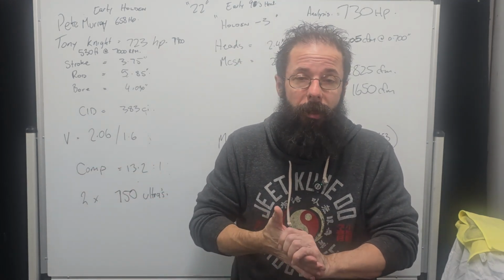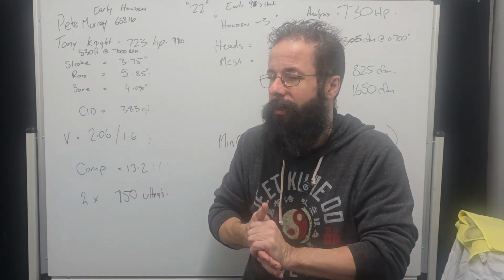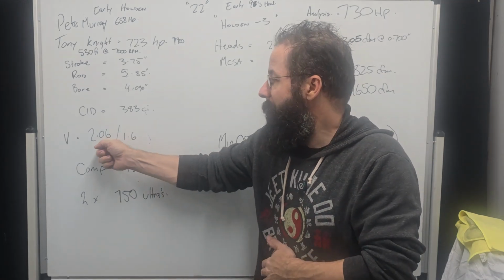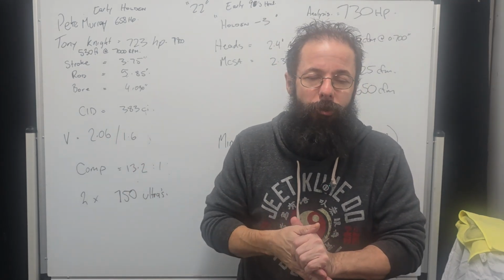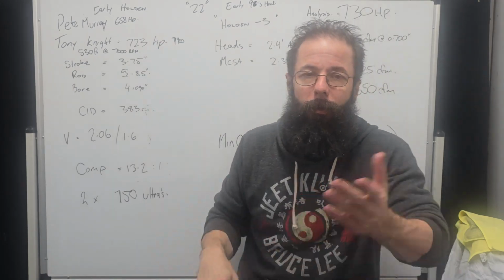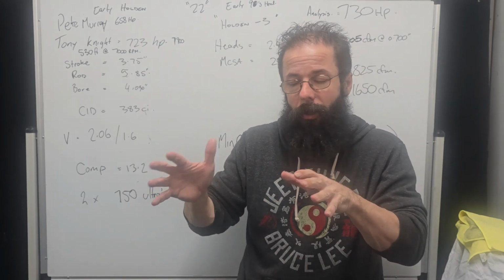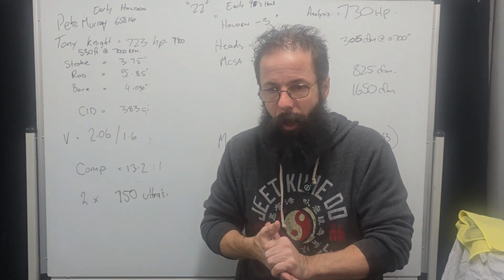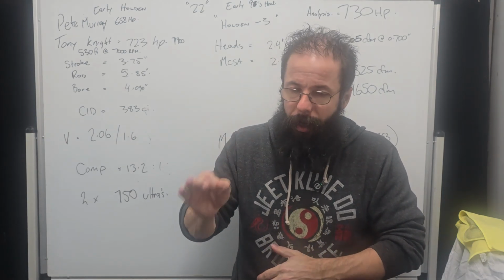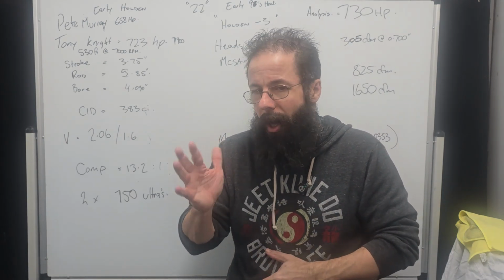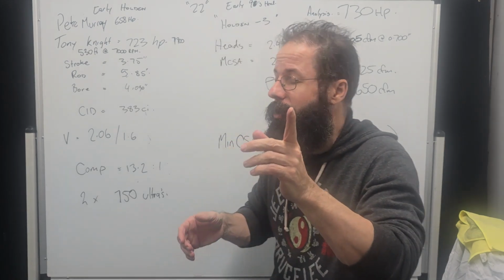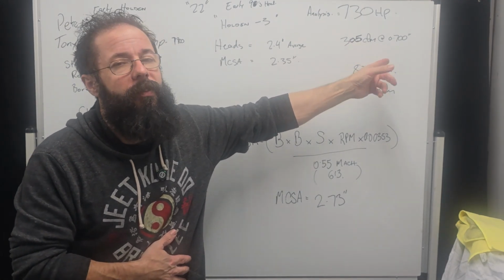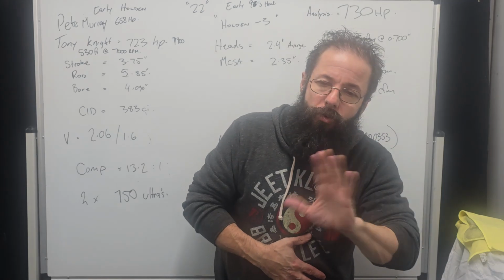Again, when we were doing these cast iron heads like 20 years ago, we really got right into it, because I used to do 11-second Holden packages and stuff back in the day when we used to do a few street cars and bits and pieces. And the iron heads, I remember, we were cutting some engines back to 202, especially because we weren't at this power level. We were doing 450, 500 horsepower street combos, really basic, 10.25 to 1 stuff.